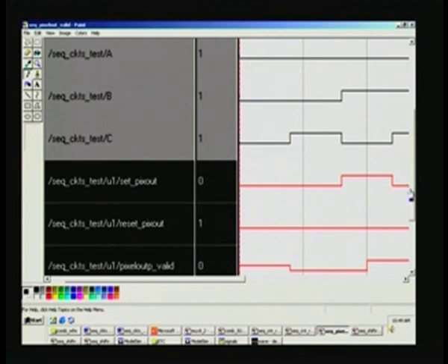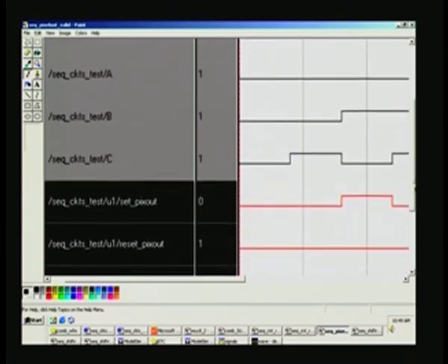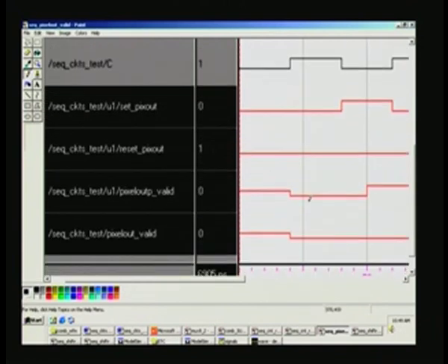Before that, let us see what happens at a reset point when it goes low. What you need to do is reset all the outputs as such. That is what is happening here in this condition, and mind you these two are assign statements basically, so they are all combinatorial outputs.